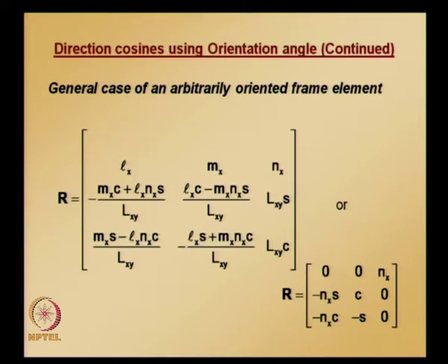So, the alternate method is third node method, in which we need to define a third node, because this third node is going to be used to define either local xy or xz plane, and whatever formula we have seen in the last class is based on third node being used to define local xz plane. So, schematically it can be explained